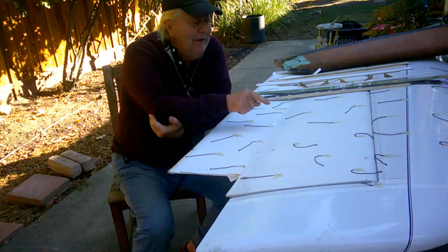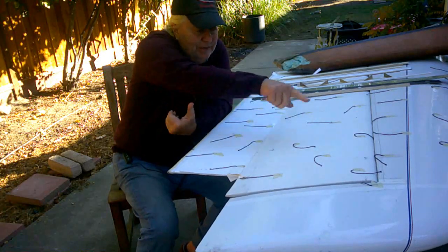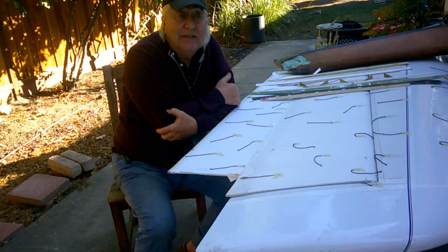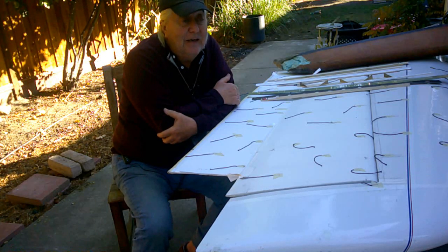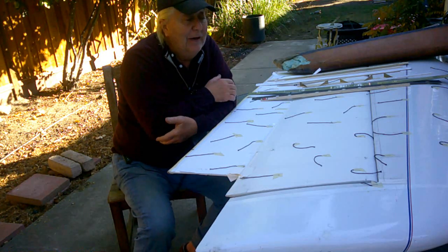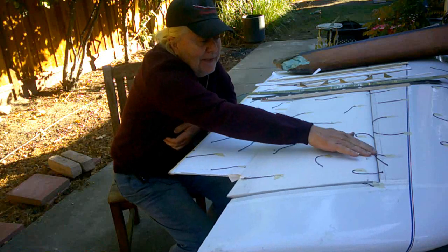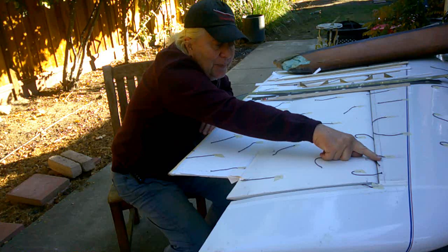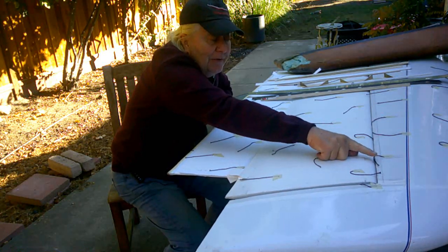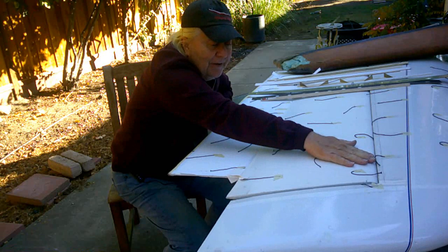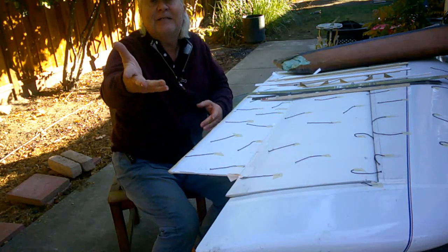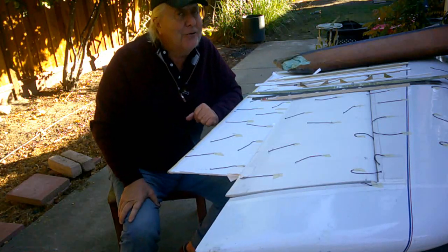So, I got out there with these elevons, no extensions, and went to test it the other day. And darned if we don't still have problems. The flow out here was good at the tip, where I put this hinge line up here where the energy of the flow is highest, because it's the highest speed flow, most energized boundary layers up here. Put the hinge here. Yeah, in this area out here, the flow is getting around the corner and going down the elbow, stays attached. Inboard, not so good.